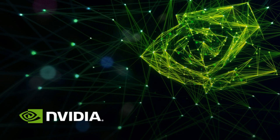What this lets us do is acquire images from the camera using the NVIDIA Jetson's ISP, an image signal processor. It's a really fast way to access data and format it if you're acquiring it from a CSI camera. So yes, we have OpenCV, and yes, OpenCV supports GStreamer. So you get accelerated camera acquisition, which is primarily what I use it for, and then feed that into a deep learning pipeline.